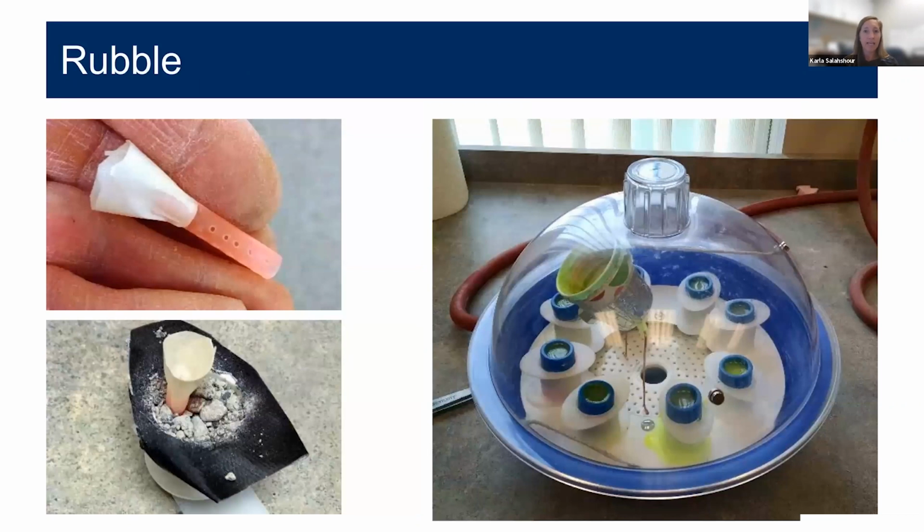Don't worry though, in case you cannot get intact samples out, there are ways that we've developed in the laboratory to handle small fragments or rubble. We can epoxy impregnate these samples either under vacuum or not. Let that epoxy cure and we can still prepare cross-sectional surfaces. But again, we really recommend you getting in touch with the lab staff to find out what size samples, what orientation of extraction is best suited for the testing that you request.